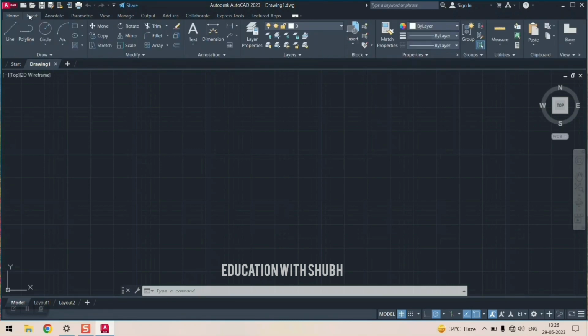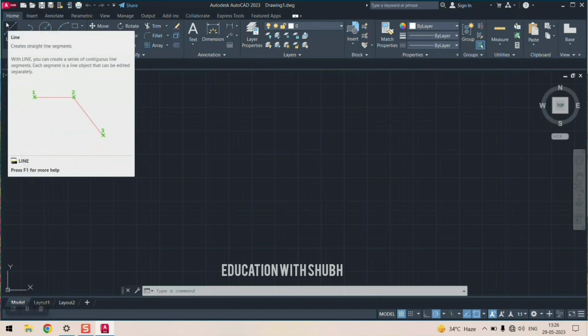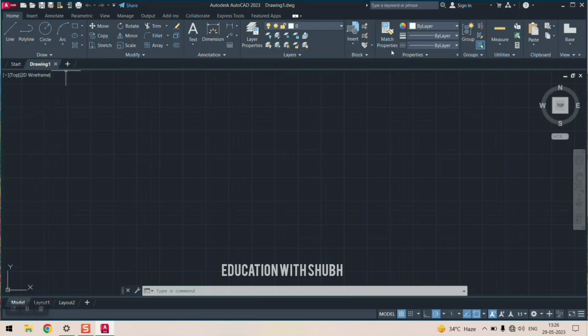So these are the different insert, annotate, home options. These are different applications which are available in AutoCAD. This particular area is what we call a panel, or a ribbon. In that ribbon, we have certain commands like draw command, modify command, annotation command, layer command, block command, properties, groups, utilities, clipboard, and view.